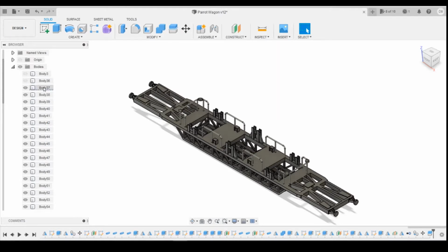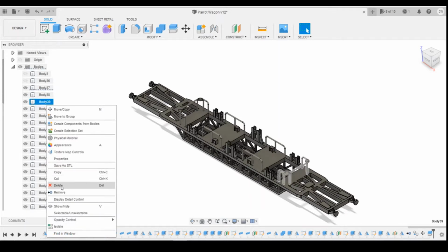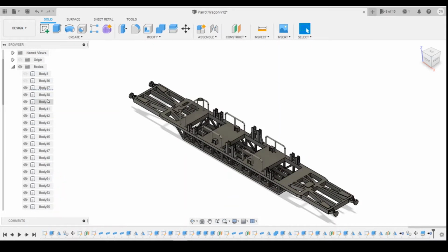We then just have to go through and remove all the parts which aren't needed. So you see 38 is needed, that's still on there. Don't need the handrails, so do remove, don't do delete, so that it's not referenced anymore. So if we remove that one, that's going to be needed, so is the plate there. The cradle is still going to be needed, but I'm just going to turn it off so that we don't accidentally delete it. Body 43 is still needed.